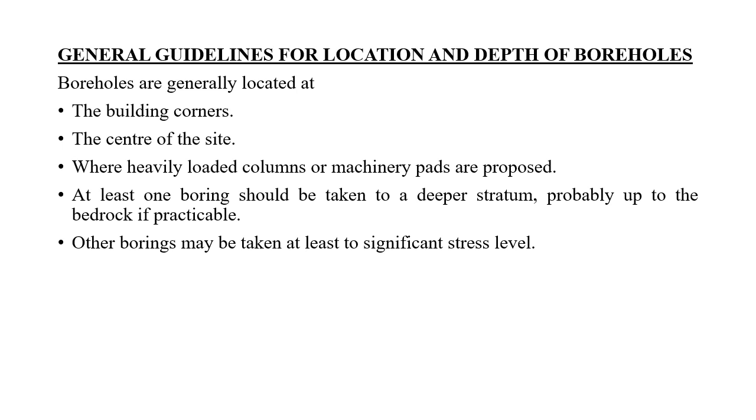This is what I said. See, significant stress level means, if you have already decided on the type of foundation, if it's a shallow foundation, you cannot go beyond 4 meters or so. Maybe not even beyond 2 meters or 3 meters. Okay, not more than that. So you already have an idea that you're going to go for this type of shallow foundation, then you have decided on the depth there itself.